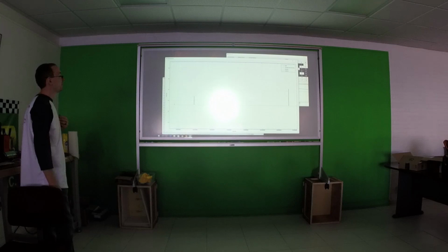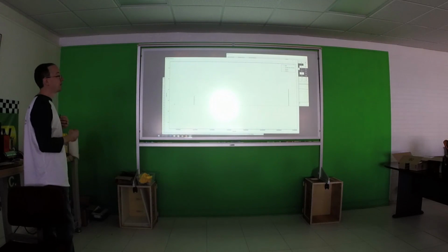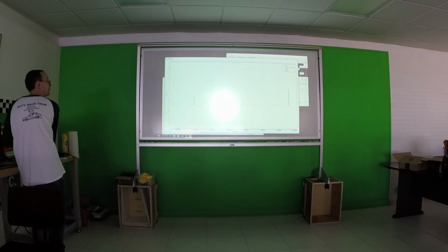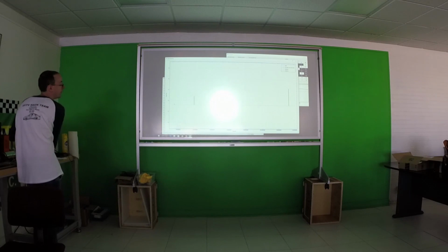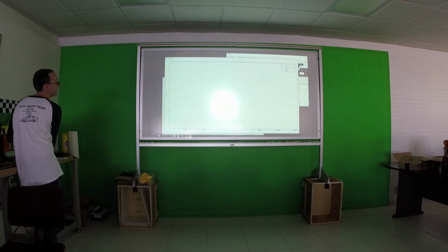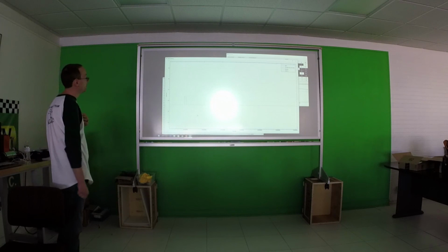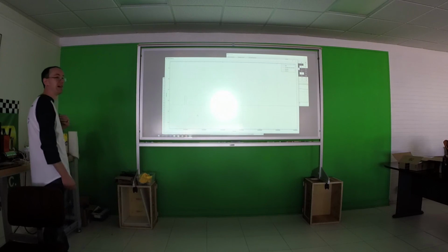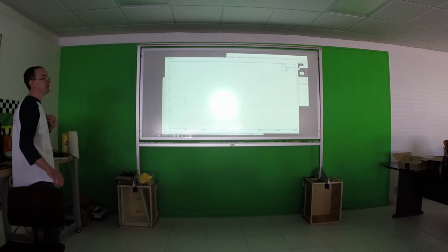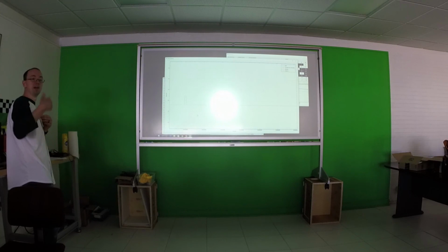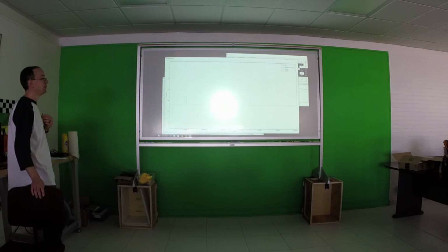The inverter, there's probably some form of feedback loop that we don't know about where the inverter tells the ECU that it's gotten the gear. Because there's a variable number of frames. Sometimes it sends 5 frames, sometimes it sends 2 frames, sometimes it sends 7. So it seems like the inverter takes a while to pick it up and issue a reply.